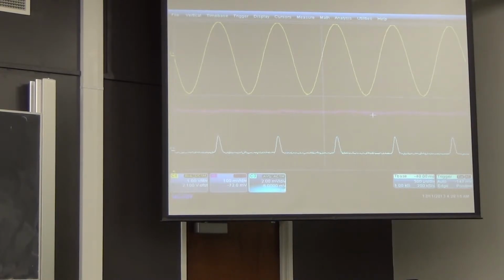Can we just see with no resistor? Because that's no resistor. Right, so this is infinite resistance. The only thing we're left with now is the charge that's lost from the capacitor due to its own self-discharge and any leakage. So we're looking at a couple of hundred mega ohms.